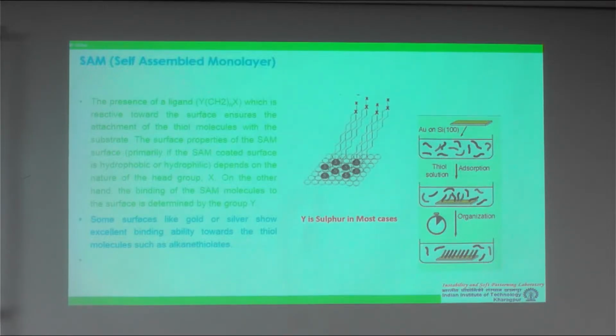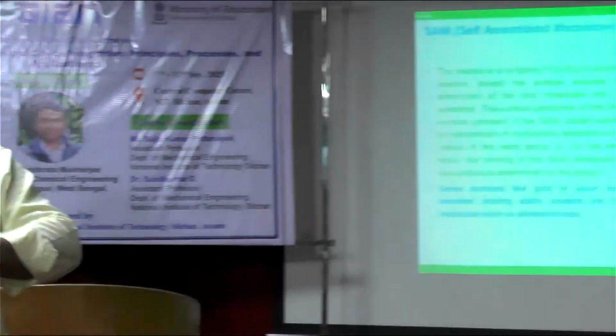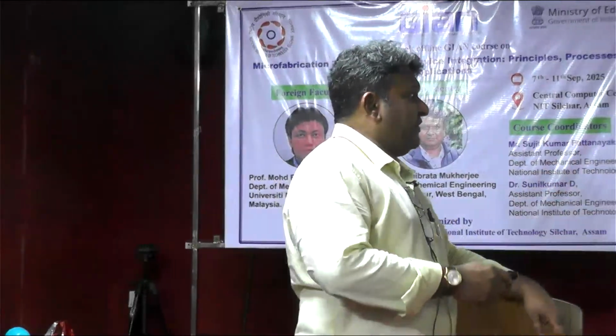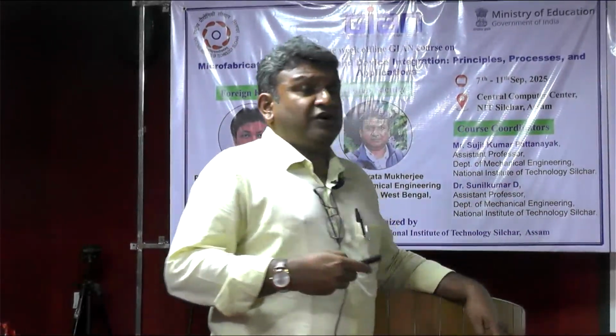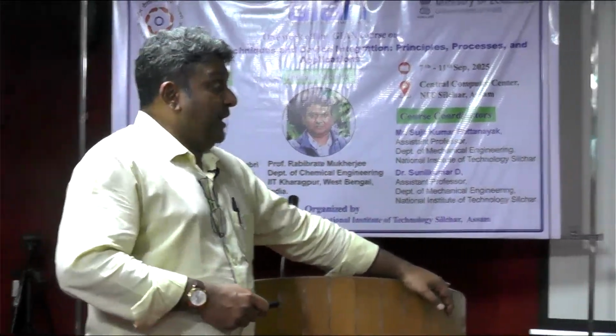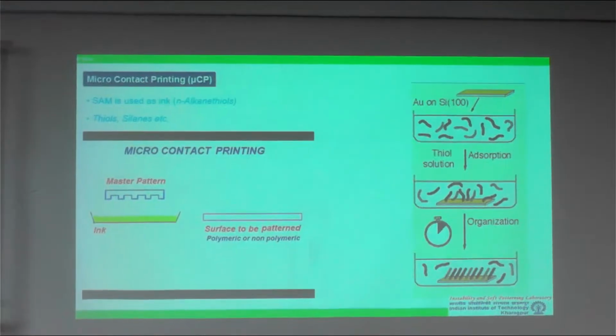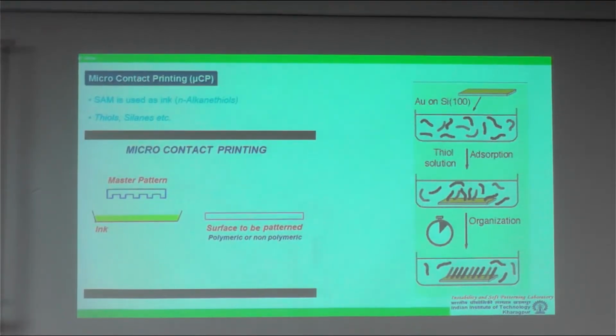What is meant by effective wettability? This surface is now covered with the SAM molecules. Now, if X is hydrophobic, then the surface will exhibit effective hydrophobicity. If X is hydrophilic, then the surface will exhibit effective hydrophilicity, right? So this is also a very interesting technique for changing or altering the wettability of a surface. Now, how can we combine this concept with that of soft lithography? So just see the video and I'll explain.